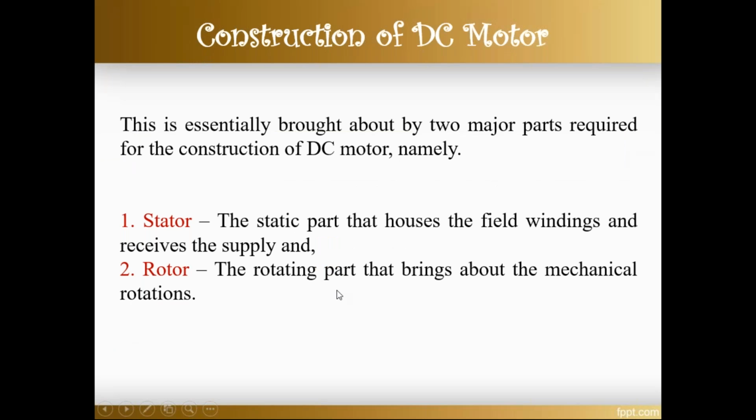Right. So this is the way of working of that DC motor. When we are giving that conducting material electricity, then it is acting as a magnet. So just now we saw that a bolt is a non-magnetic material. When you are giving that energy, then it is acting like a magnet. Now, based on the terminals, if you interchange the terminals, plus to minus and minus to plus, you can change that rotation direction.